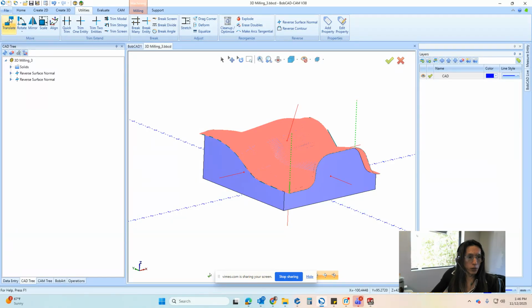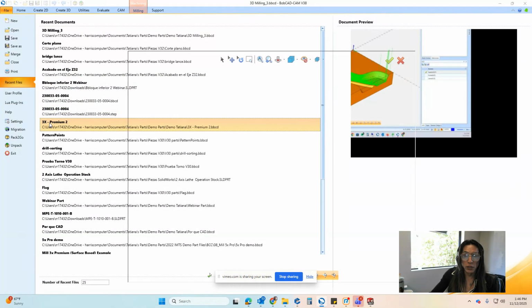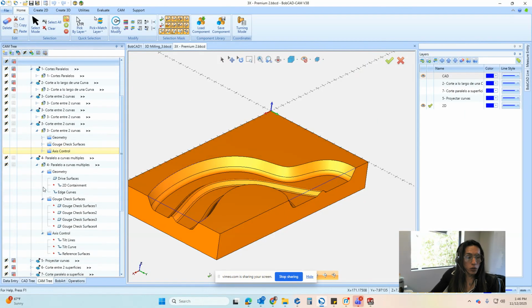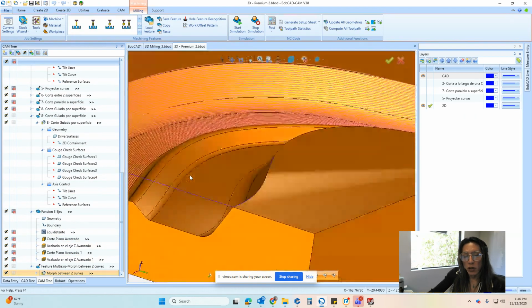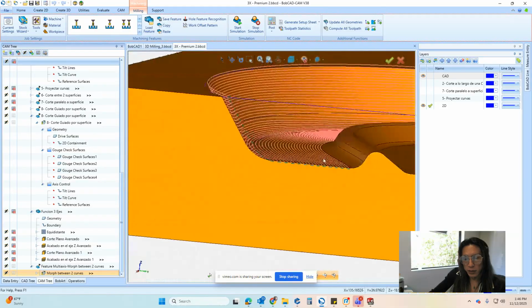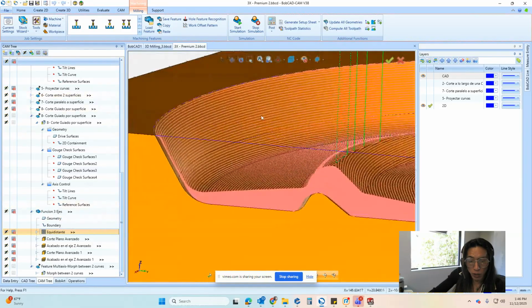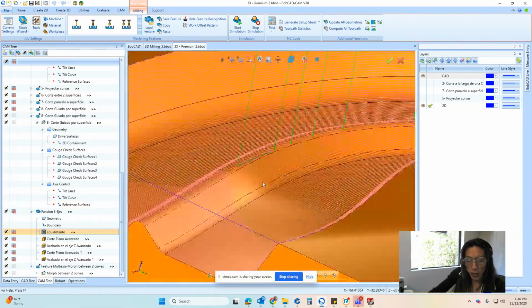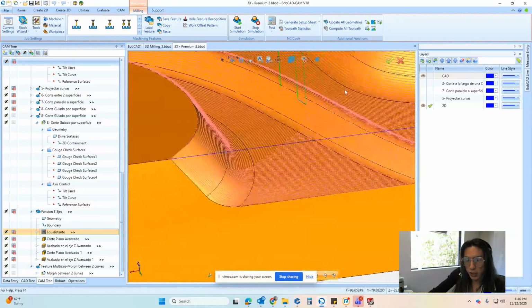We covered this on the prior webinar that I did on premium, but I like to take some time to show this. Premium toolpaths also have a better way of blending or morphing between two surfaces, like you see here. This is very difficult to accomplish, because the equidistant strategy will follow and blend, but you will always have these direction changes that you can see here and here.